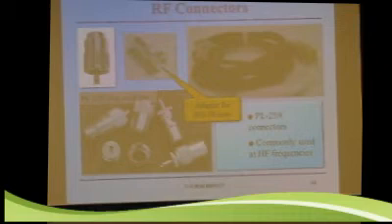This is what the SO239 jack is. The PL259 is the plug, if you want to call it that. Then the SO239 is the jack, that's the UHF connector family, typically used up through about 2 meters. Once in a while you'll see something in 440 for it.